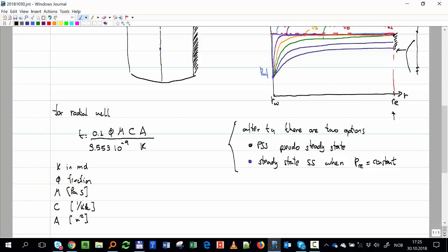So it depends on everything, right? Depending on the length of your well, on the area of your well, on the viscosity of the fluid, on the compressibility, if you have gas or if you have liquid. Remember that the compressibility basically tells me how quickly pressure changes travel in the fluid. If I hit the fluid someplace, that is going to propagate, and how fast it goes is defined largely by the compressibility.